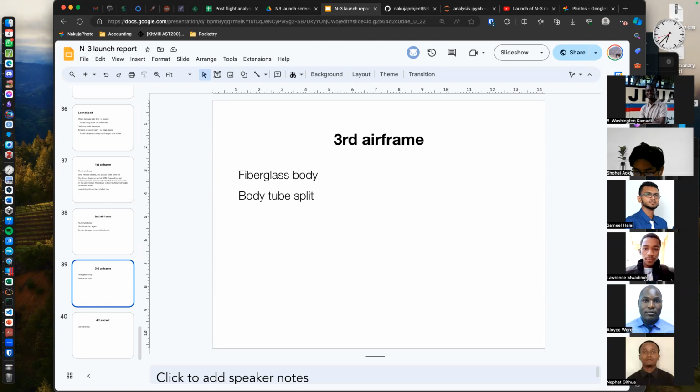So there is an element of, if you look at how we were joining the parts, the way we were bolting, you find some of the bolts were highly protruding on the surface. So there is an element of interference, like the airframe body was not smooth and free to move about. There is a likelihood of interference due to protruding nuts that could even get stuck on another part of the launch system.